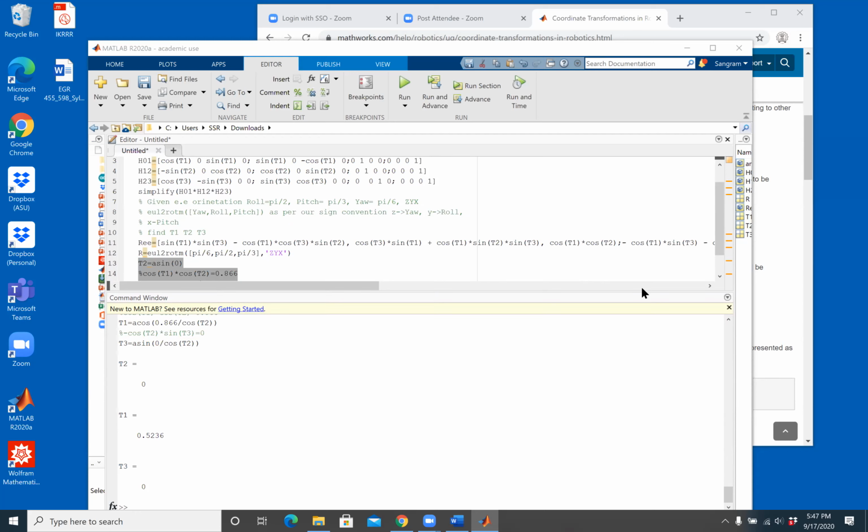Calculation of the homogeneous transformation matrix of the end effector. The end effector has certain positions and certain orientations. End effector orientations are input to the spherical wrist problem, and end effector positions are input to the inverse kinematics of the first three joints.